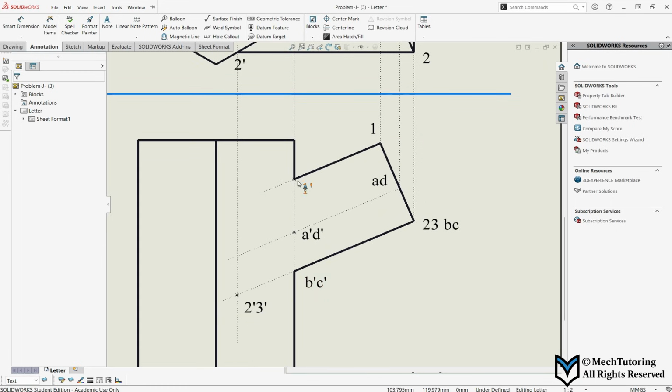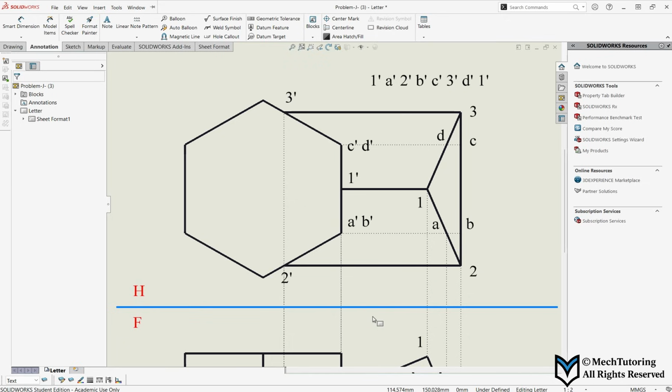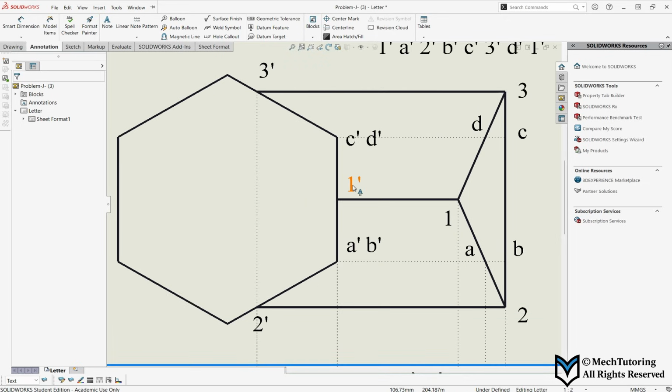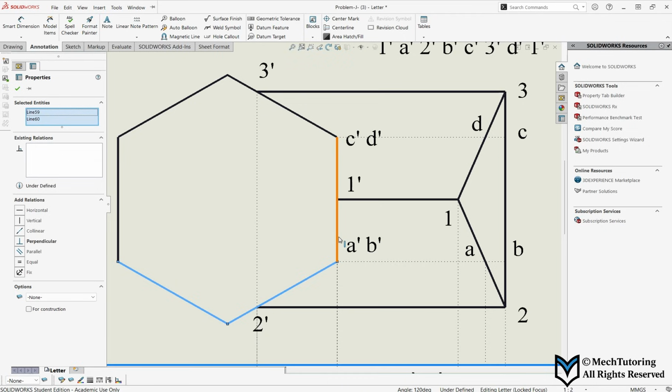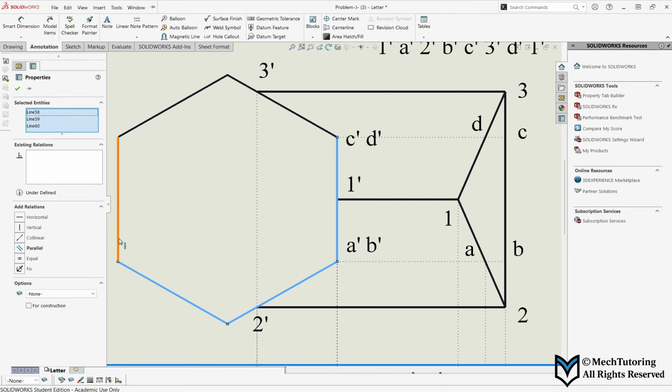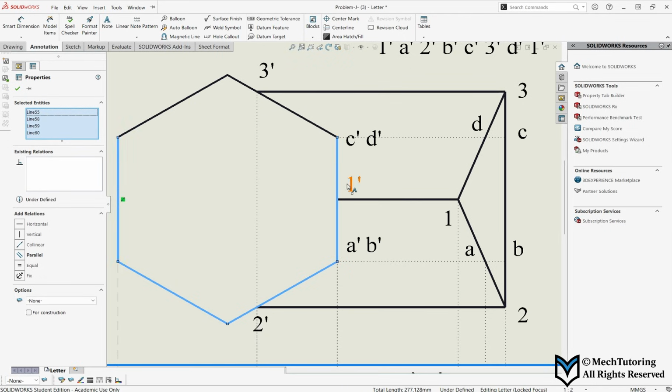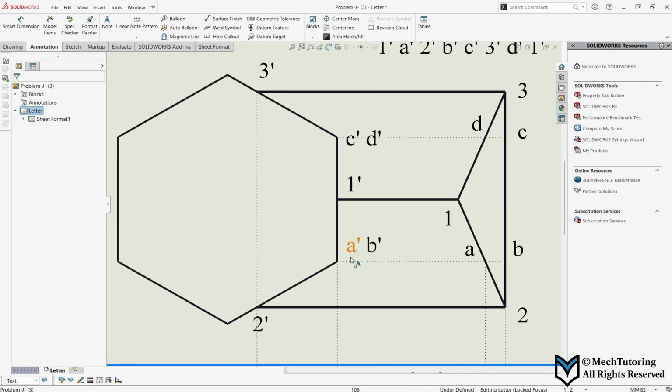Now, once you got all the points, you have to join them with solid and hidden lines. How do you know something is solid? When you connect 1 prime with 2 prime, it is in the front of this hexagonal face. So anything on this line, this line, this line, and that line will be solid. So if you go from 1 prime to 2 prime and then back to 3 prime, but it's passing through the corners, is it? So let's count the points in between also.